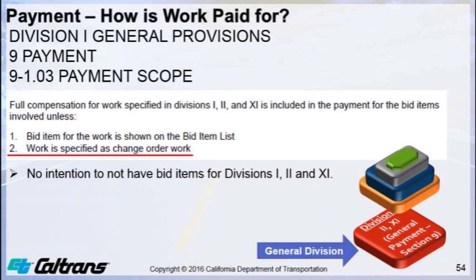There should be a bid item for work in Division 2 except when the work is incidental to other construction activities or the work results from how the contractor wants to perform the contract item work. Contracts should have bid items for Division 2 work such as traffic control, providing a biologist, removing known hazardous waste, stormwater prevention plans, stormwater BMPs, and the other environmental requirements.